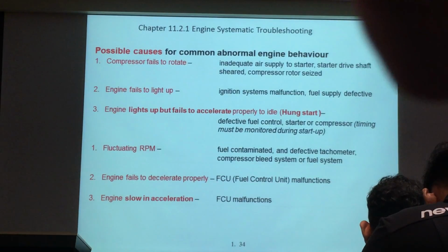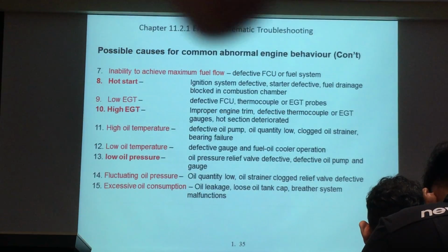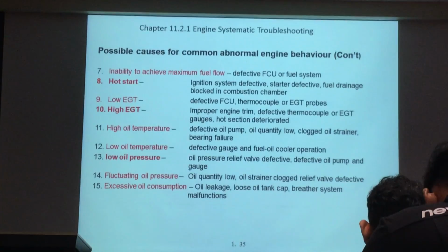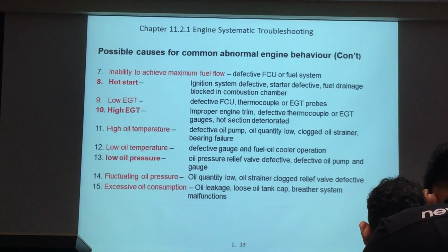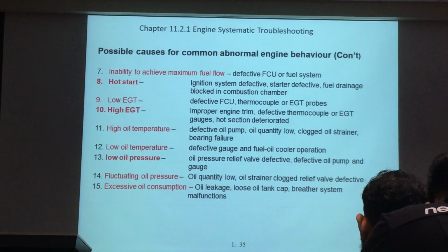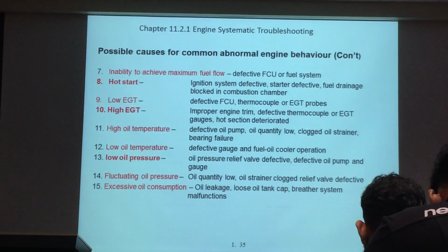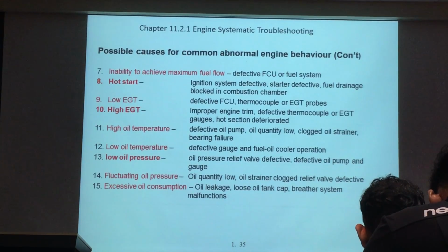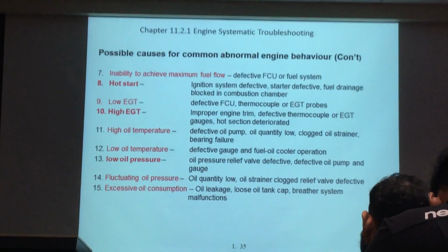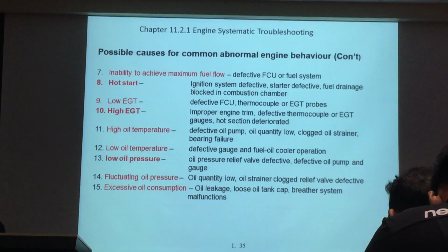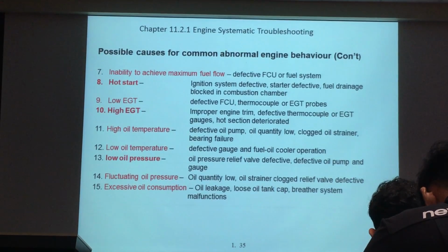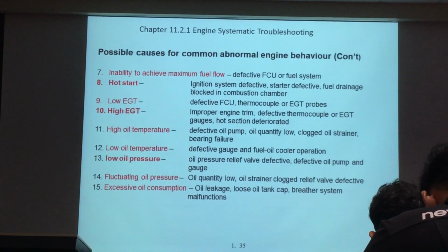The last one is low oil pressure. After engine start, oil pressure will increase slightly. With no oil pressure, the engine has no lubrication, so you cannot continue the start. You must abort the start, because oil is the only lubrication.